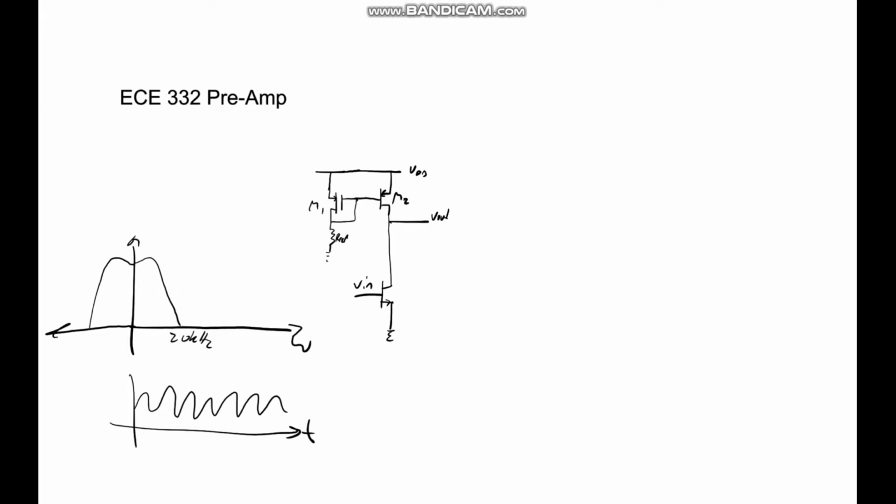We can now start talking about the baseband signal that we start with. It's going to be a voice signal, so it's going to be somewhat band limited to about 20 kilohertz. So we have a current source set up here. Our voltage gain is going to be gm times r0. This is gm, then r0, so gm r0. And r0 is the output resistance.